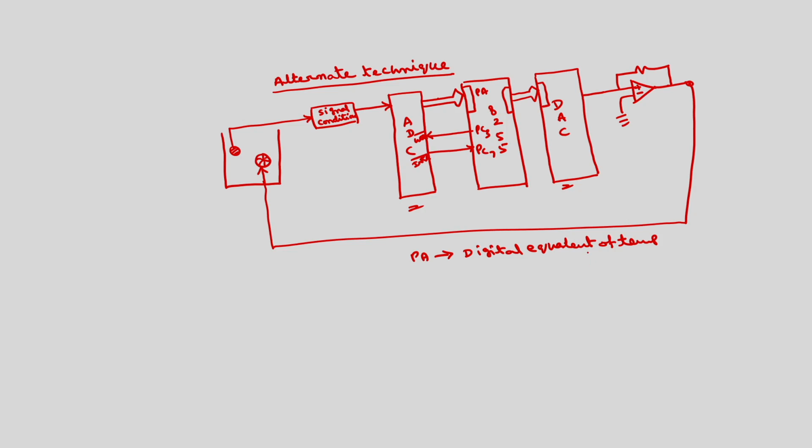So, here we do not have the limits now. I do not want to control between 30 degrees and 60 degrees. I want to maintain at a particular temperature only. Based on this, I want to maintain a fixed temperature. Whatever value we get here, if this is FF, it means the temperature is high, so I want to reduce the temperature.